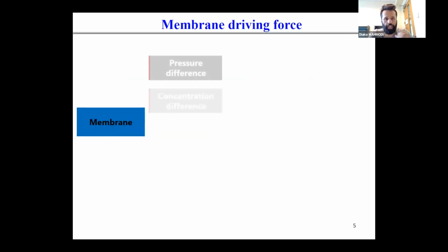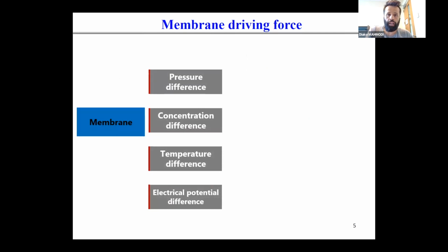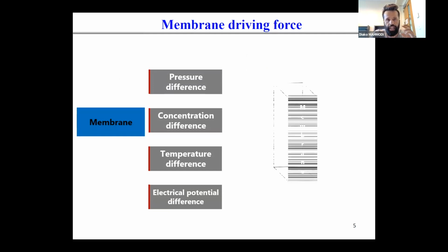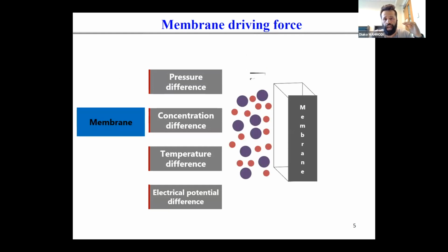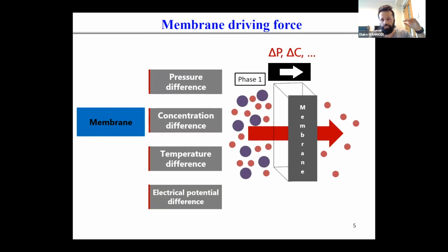Membrane driving force. In order to work with a membrane, we need a driving force. We have pressure, concentration, temperature, and electrical potential as driving forces in membranes. And always we have flow from phase 1 to phase 2, from high to low pressure, concentration, and temperature. That's why we can take advantage of membrane technology for the filtration process.